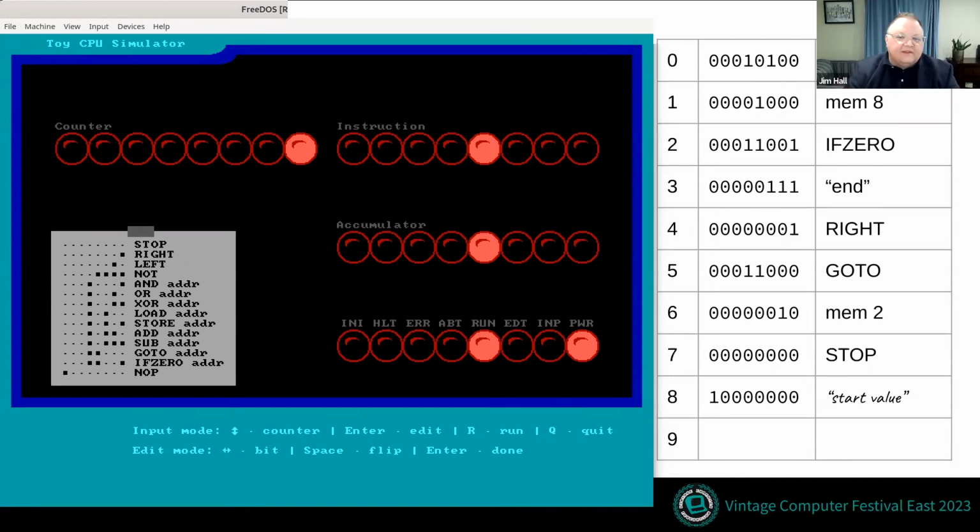And so because I got this delay built in, I'm able to talk through it with my students. And so now we can see that it's, where am I here? So this is I'm moving the bit to the right. And so it's testing if it's 0, and if it's not, it's going to keep going. And then it's going to keep moving our bit to the right with that right shift instruction. And so that's the right shift instruction there. And now it's going to right shift one more time. And then there's the right shift instruction. And now that 1 becomes 0.